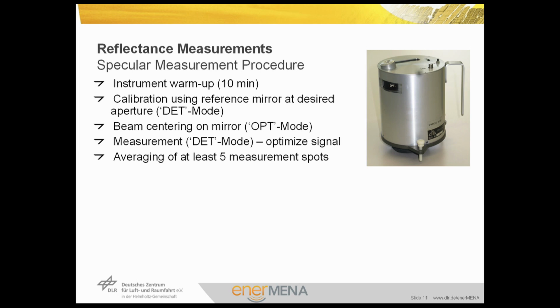But in the field of an actual solar power plant, it is important to monitor the reflectance of the mirrors over time, because this value is needed to evaluate the efficiency of the power plant, to evaluate degradation, and also to monitor the soiling rate. So for this, we use portable specular measurement instruments. In this case, the same as before, the Devices and Services reflectometer.